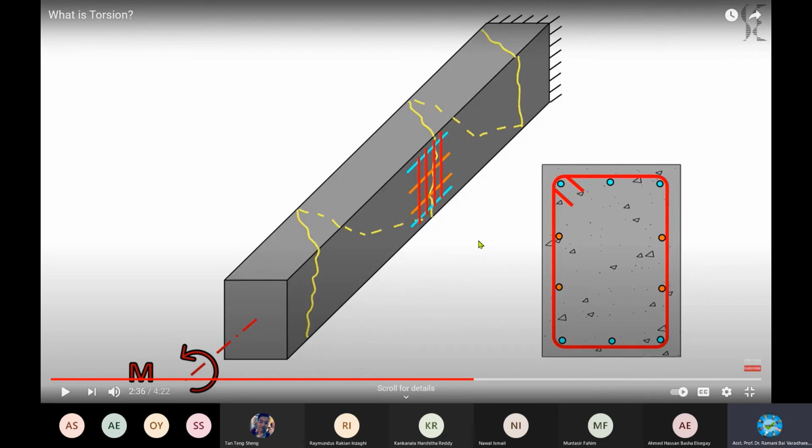Okay, all of you have to imagine this as perpendicular to the slide. Here, this stirrup, which is putting all the reinforcement in place, these stirrups, and sometimes, if it is heavy shear loading, then they will also add these orange color bars to take up the shear load.